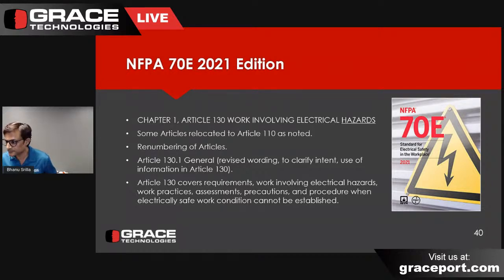Now, the energized electrical work permit is the same in Z462 and 70E, and there were really no changes, but I just want to comment that the energized electrical work permit is completely misunderstood and misapplied wherever I go, right? So a heads up on that, again: the energized electrical work permit is not required for all energized electrical work. There are exemptions, all right?